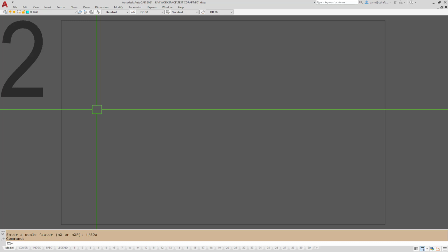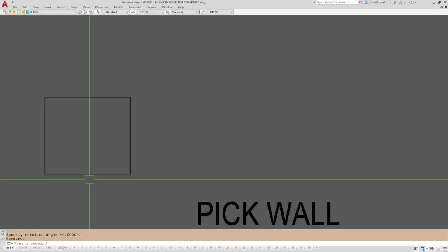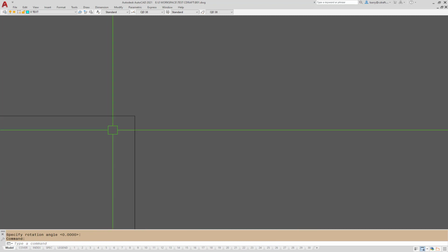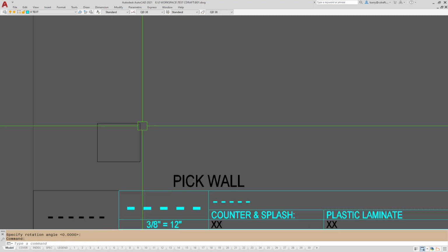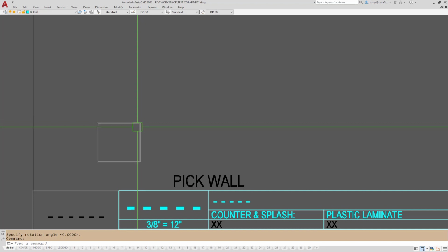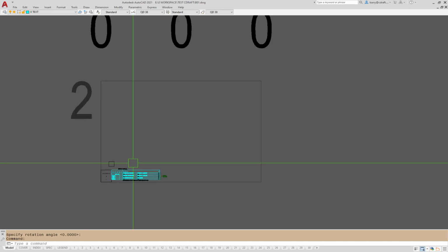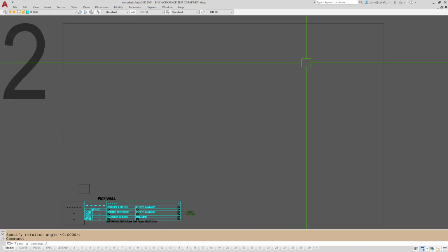Now the first thing I want to do is add a tag. So that's TG spacebar. When I insert the tag, that's creating a base point, an insertion point right here, top right corner of this offset. So notice I'm going to move my cursor off to the right hand side of the screen, out of the way, and from here on out we're going to type in with prompts, and it's going to draw it in with an auto insert at that base point, at that insertion point.